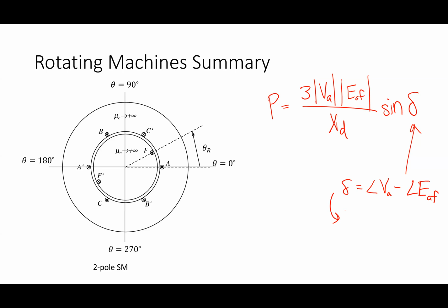So basically the rotor shifts itself over time to make sure that it's providing the exact right amount of power. We said that if I increase the power going into the machine, the angle delta changes itself over time to make sure that I provide just the right amount of power that is needed to go onto the grid if this thing's a generator.